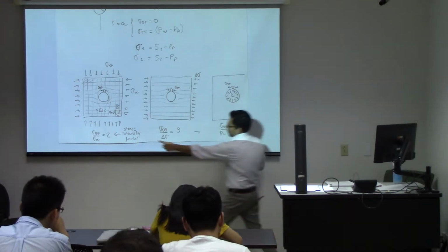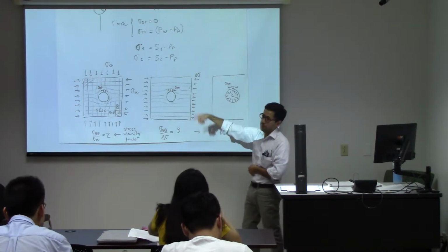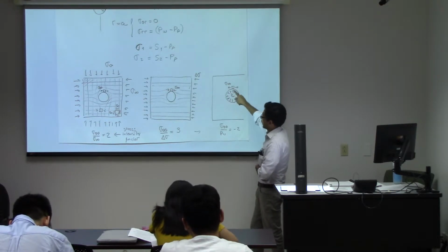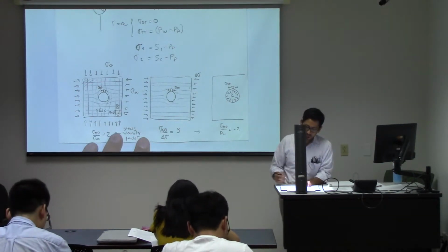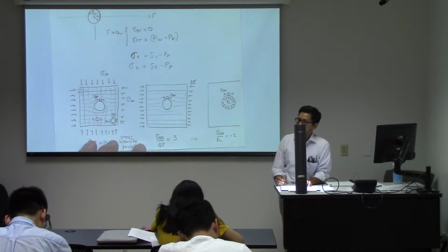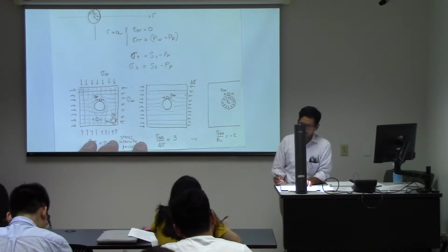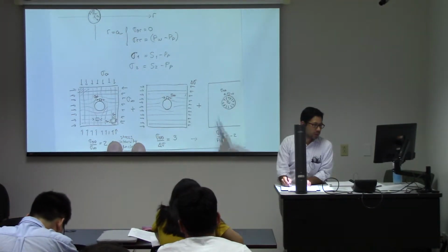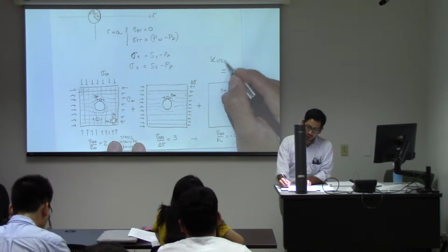Notice that these two are the same because these two cases are isotropic cases. So before we had isotropic stress around the solid, now we have a pressure which is the same in all directions inside the wellbore. And the wellbore solution, the Kirsch solution, how it is solved, I used to do this before, but it just takes a lot of time. And you can see it in my notes. It's just adding this solution to that solution to this solution. And as a result, you get the Kirsch equations.